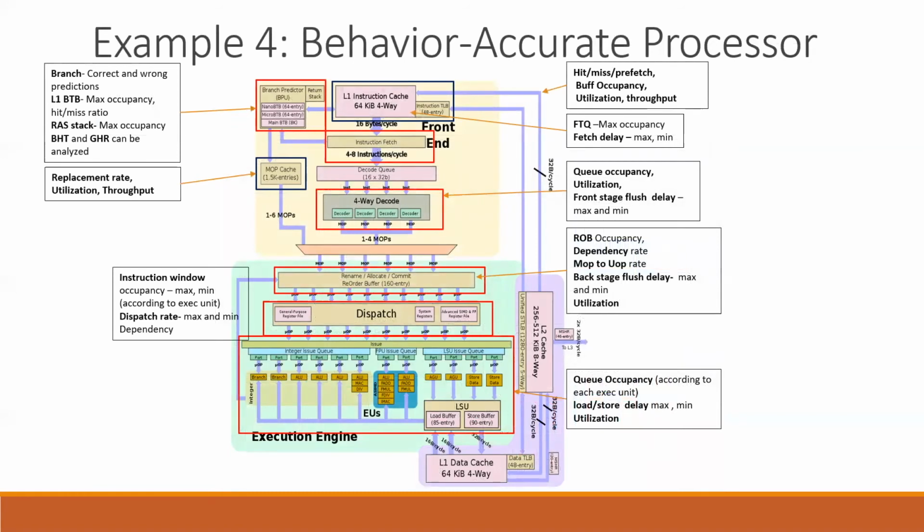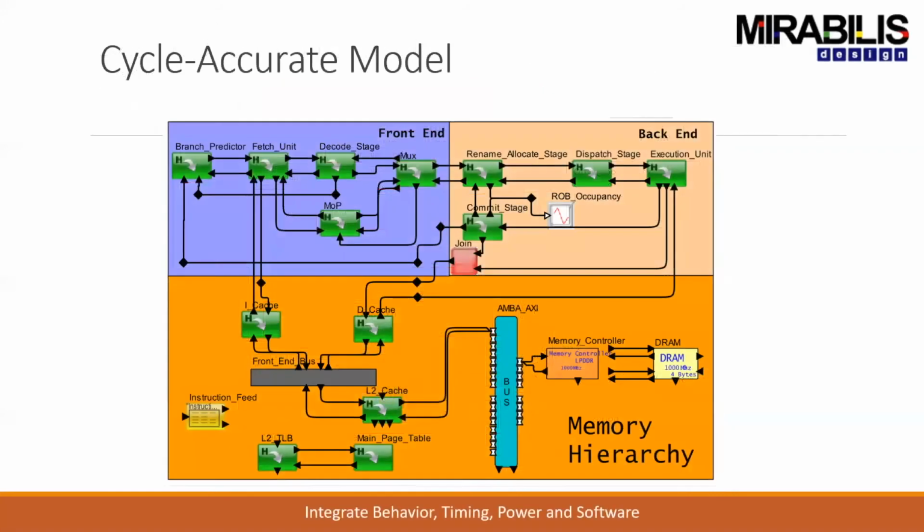The last one is that I can go down into a particular IP. In this case, we're looking at the internals of a particular pipeline of a processor core. You can see how all these different stages have different requirements in terms of analysis and parameters. We have modeling components that represent each one of these as part of the hybrid processing library. So you can now assemble the core not as just one component, but as a system of components. You can actually see what is happening in each stage within the pipeline, and that way fine tune the architecture so you get extra performance.